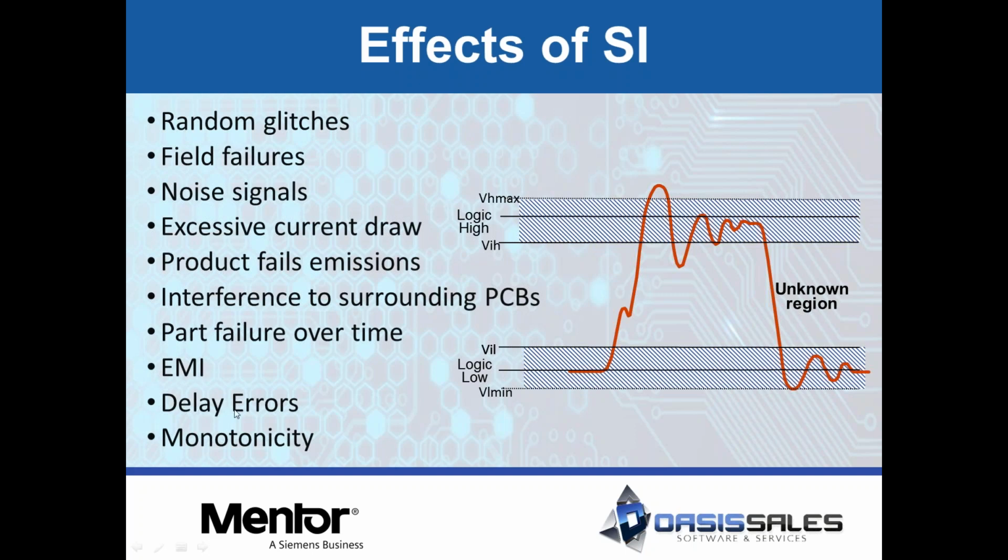Again, I mentioned EMI, delay errors, getting timing problems due to crossing logic levels. And then, due to multiple receivers on a line, you can get ringing in the transition area of a signal, which can obviously cause a lot of these issues as well.